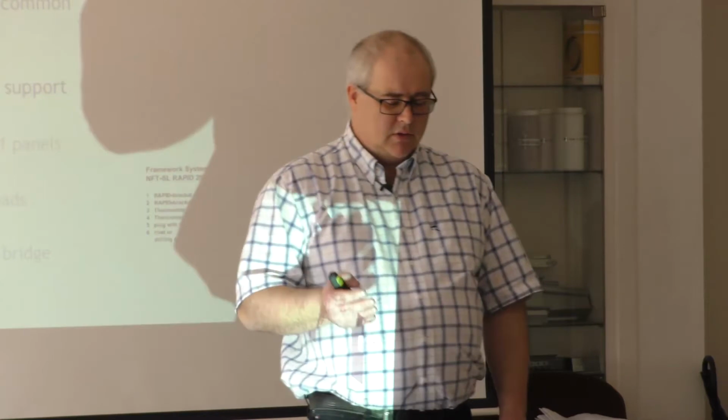Do you ever get up in the morning, it hasn't been raining, and you go out to your car or on your lawn, and there are damp patches from overnight condensation? It's called nighttime condensation. What can happen with aluminium frames, if the boards are tight up against them, is that you get this nighttime condensation on the face of boards. When you look at the job, you're going to see wherever the framing is behind it, because that area of the board is a lot colder than the other areas next to it.